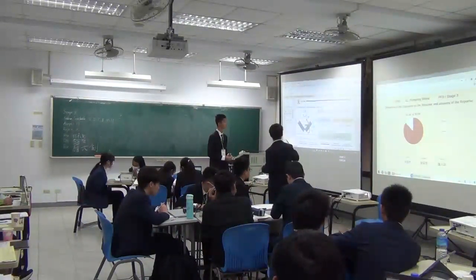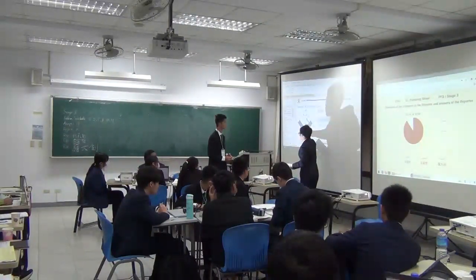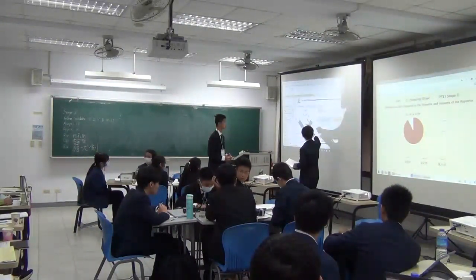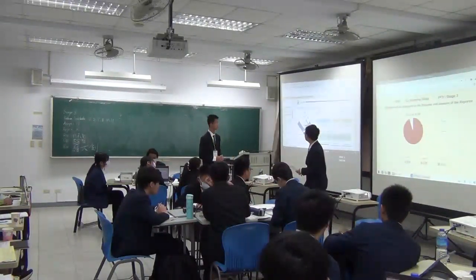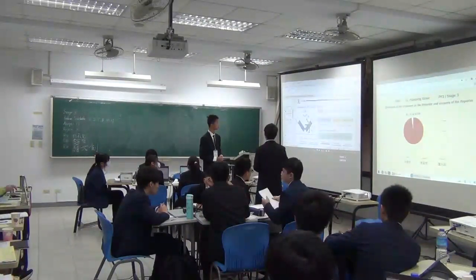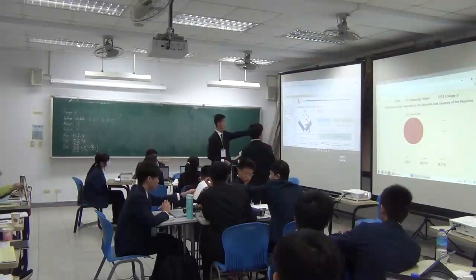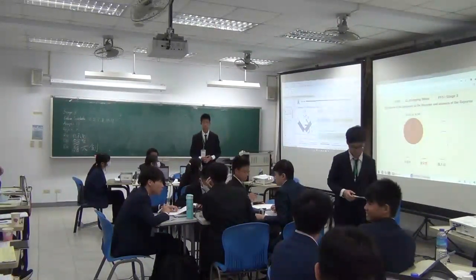Okay, so in the figure here, what do you think is the velocity of fluid right here? 0. And the velocity of fluid here is the exit velocity, yes, just stated. So you did not consider continuity when you're doing this here. I mean, the area is the same. Right? Yeah. Okay.